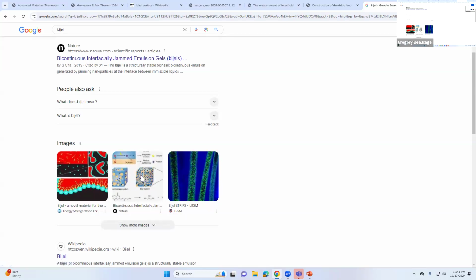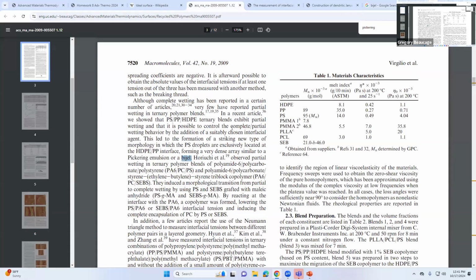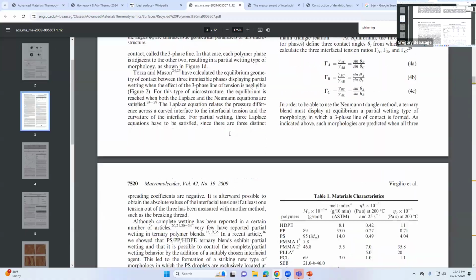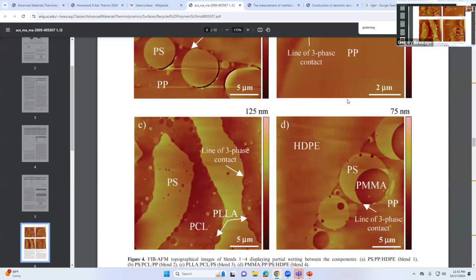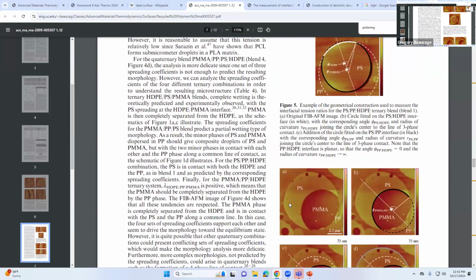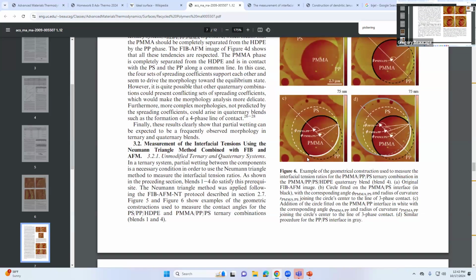You have a combination of spinodal decomposition and the surface energy thing coupling together. This isn't necessarily unique; this business of the surface decoration, like a Pickering emulsion, is something that happens a lot. Like you put filler like carbon black into butadiene rubber with SBR phase, they're immiscible. So you have the three things mixed together, and the carbon black is supposed to reinforce the rubber, but in some cases, it'll just do this Pickering emulsion thing and decorate the SBR phase.